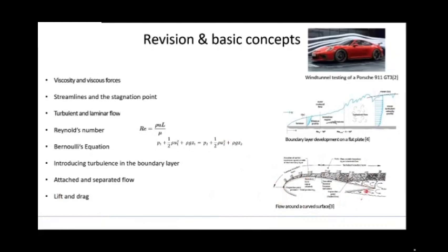Conversely, if we see a reduction in pressure on the bottom of the object, clearly that would generate downforce. So generally in automotive terms, we would talk about downforce, so negative lift, and in aerospace terms, we would talk about lift, the idea of trying to increase the height of our object, trying to raise it up in the vertical direction.